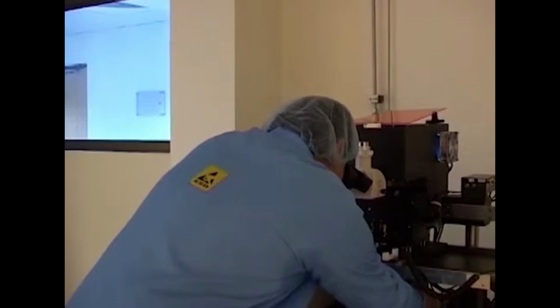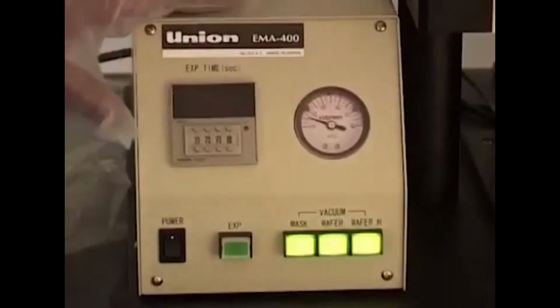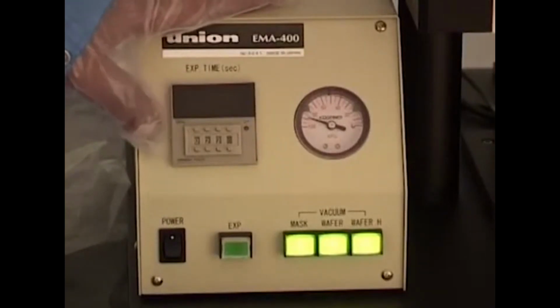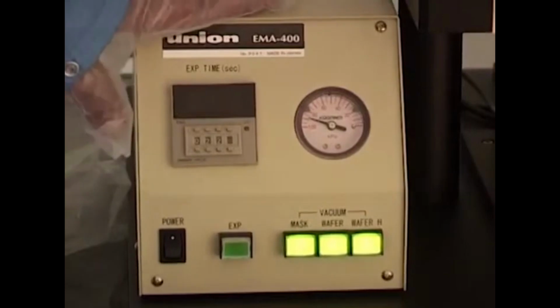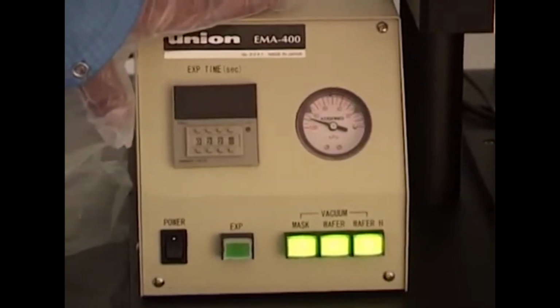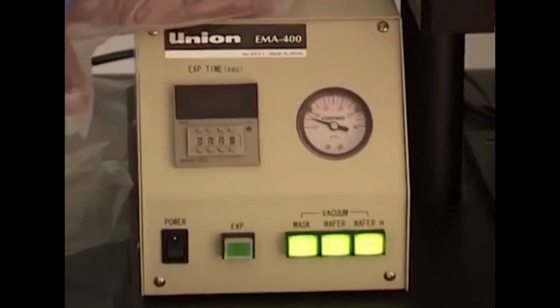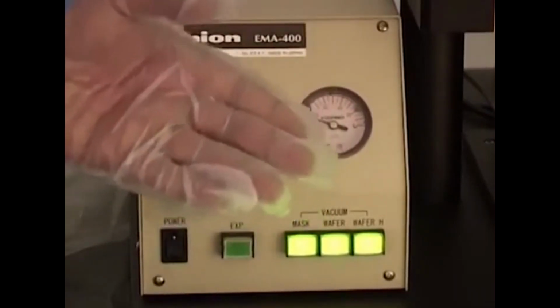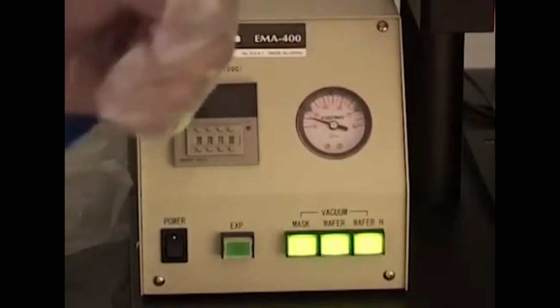Now I think we have a pretty good adjustment, and we are all set to do the exposure. This right here is also a controller for the exposure time. If you look at the resist manufacturer sheet, it gives the exposure dosage for a certain thickness of the resist film. So what we need to do is calculate from there, using lamp power, how much exposure time is needed for the particular thickness that we are operating.